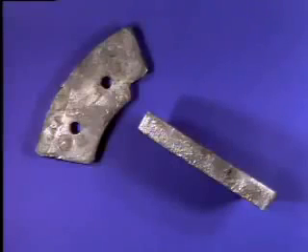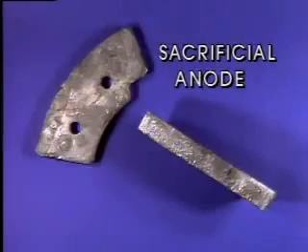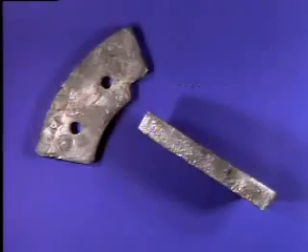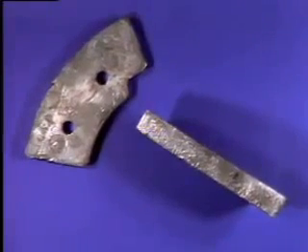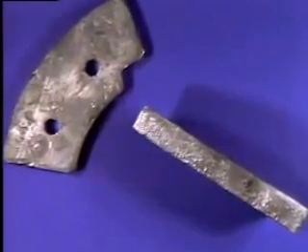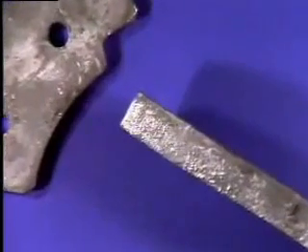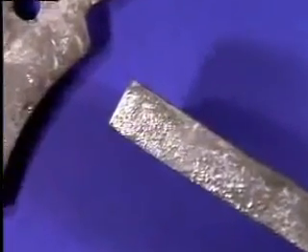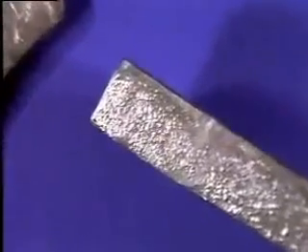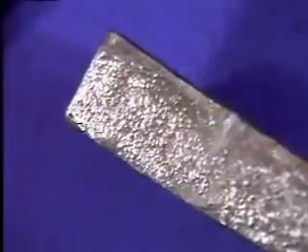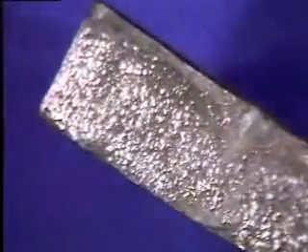Another method of controlling corrosion involves using a device called a sacrificial anode. When a sacrificial anode is used, impurities in water tend to react more readily with the anode than with the metal of the heat exchanger. So the sacrificial anode corrodes while the heat exchanger is less affected. Heat exchangers that are used with water often have sacrificial anodes made up of zinc plates mounted inside.